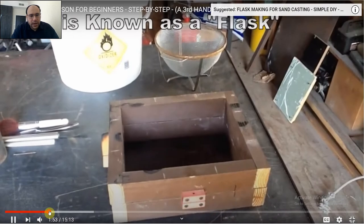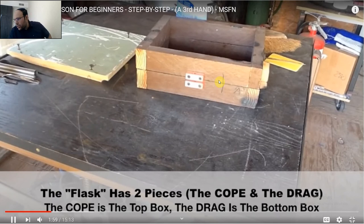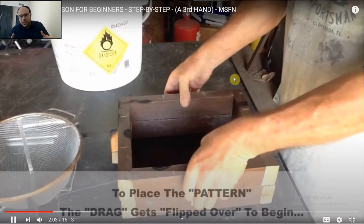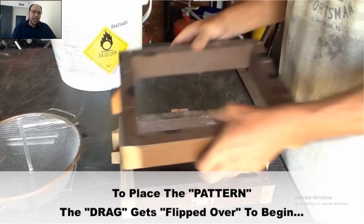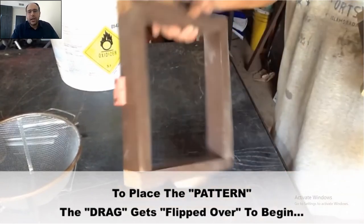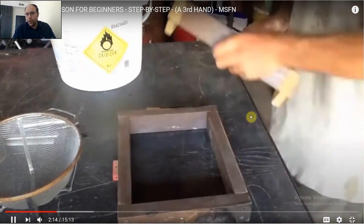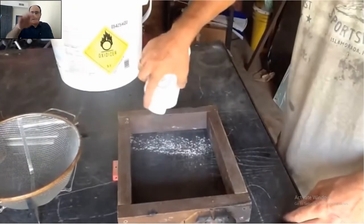Okay. Now what he is doing, these two things here, this is known as the flask. The flask is made of wood, as already shown here, for some simple castings. For bigger castings, we basically make this flask from metal, like cast iron. And this flask, as already shown here, is two pieces, two parts. One part, and there is another part.